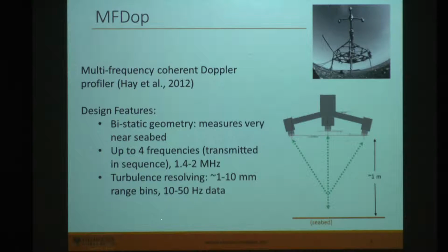It's a nice rugged instrument. And the way it's deployed is generally we put up a frame in the nearshore. This frame happened to be at about the mid-tide level, so later on it was covered in water. And the instrument itself is mounted about a meter above the seabed, and it makes a profile of velocity, size, and sediment concentration on millimeter scales with tens of hertz resolution in time, and all the way down to the seabed, so boundary layer processes.